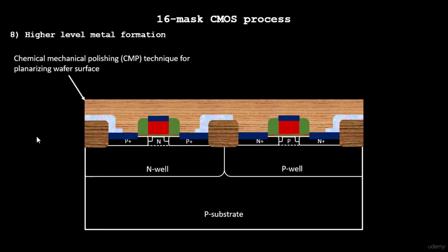And now we have etched off the surface. Now the gate and the source and drain are open for any type of contact building that we want to do. Okay, so let's start with the local interconnect. There are various steps to do it. The first step is to deposit titanium. Titanium is a metal which has very low resistivity.